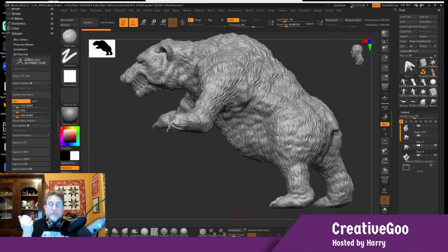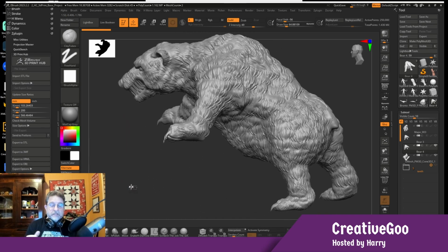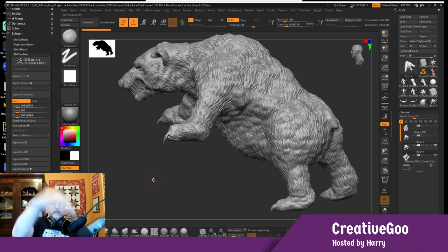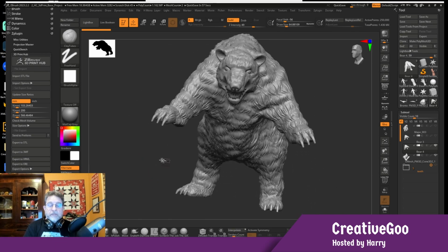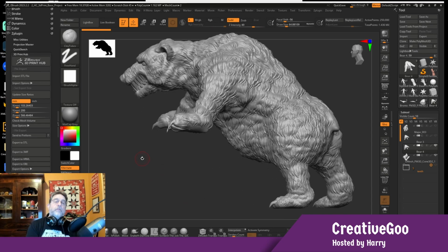He is not, and so once he's printed, you're going to have to drill holes in his feet to mount him to a base for him to be the most stable, because he's going to be heavy in the front. You might even have to put a washer underneath the base so that he doesn't overspill a base if the base isn't big enough to hold the whole model. So those are things to keep in mind when you're modeling for 3D printing.